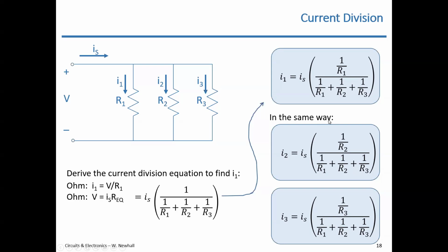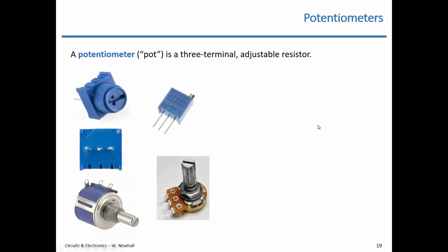So going back to voltage division and applying that, let's talk about potentiometers. So potentiometers are three-terminal devices, and you could think of them as an adjustable resistance, or actually two adjustable resistors, as you will see. These are often used in some kind of human interface, like a volume control or the adjustment of a voltage. If you turn a knob on something to adjust the volume or some other parameter, you might be turning the shaft of a potentiometer.